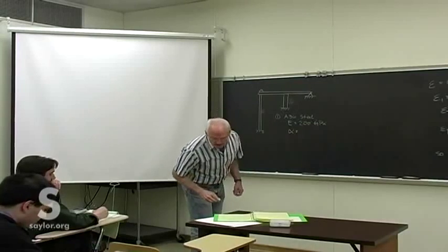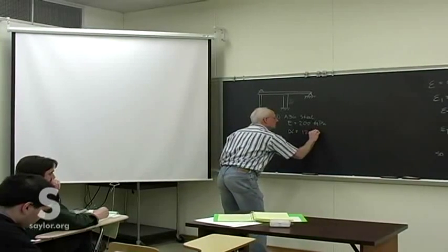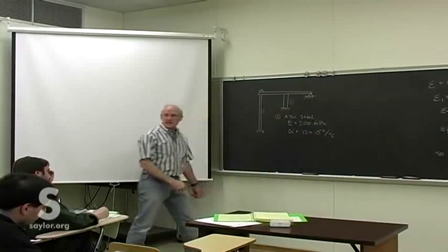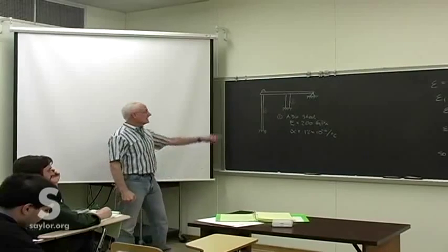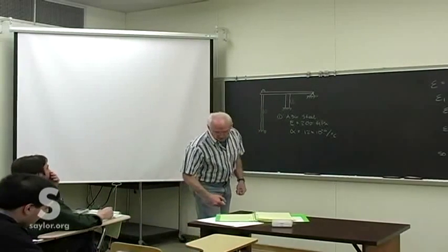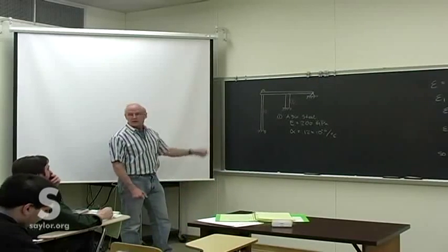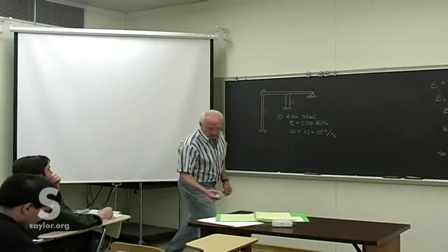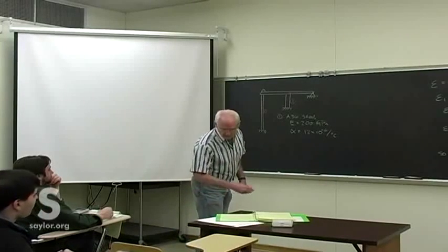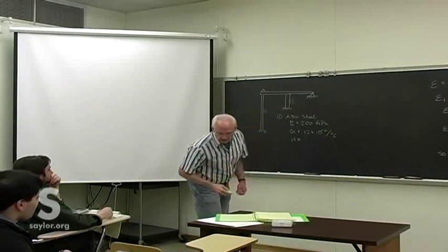Coefficient of thermal expansion. Actually, we're not going to model any temperature change in that piece. We're going to put all the temperature change in piece 2, as if this was some part of a structure and for some reason 2 would heat up and 1 wouldn't, which for buildings could be a concern because you'll have part of the building in sun and part of the building in shade. So you have to get these pieces to fight against each other sometimes.